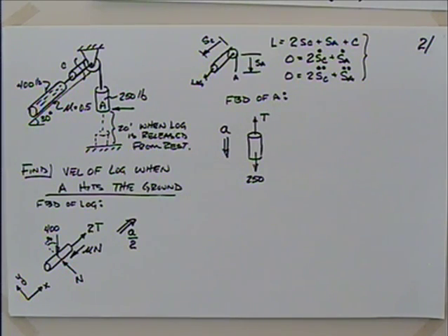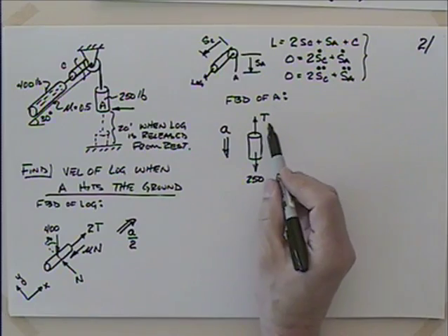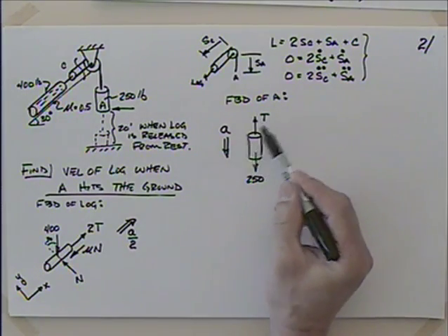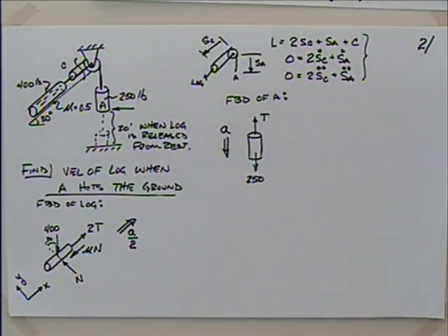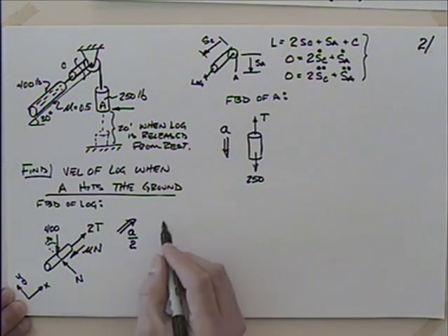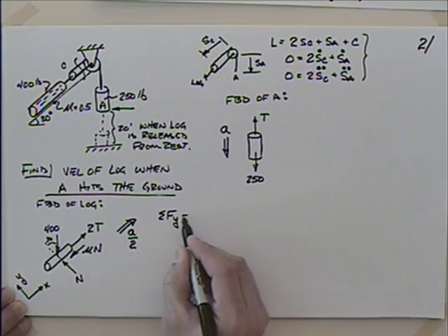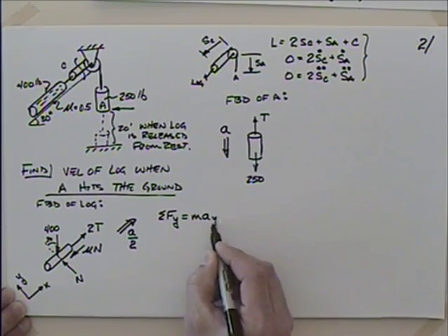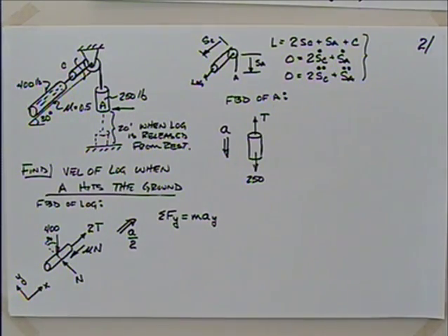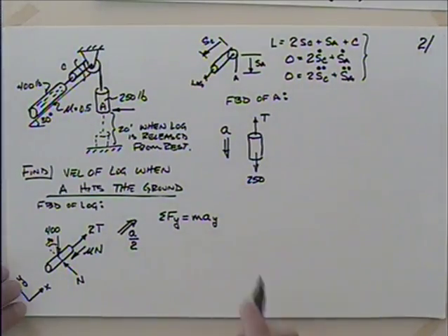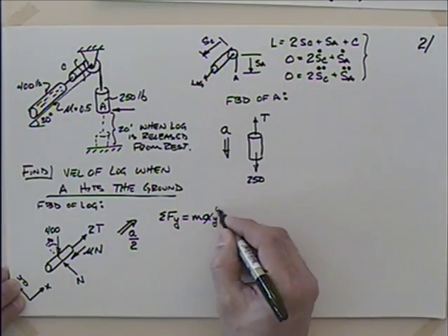So let's see. We've got another equation in the vertical direction where we can relate the tension and the acceleration. I think we've got a shot at this. So coming back over here, if I sum the forces in the y direction, setting it equal to mass times acceleration in the y direction, what acceleration in the y direction do I have? Hopefully 0, right? I mean, we're hoping the log's not bouncing up and down as it's going up that ramp. We're hoping the acceleration there is 0.